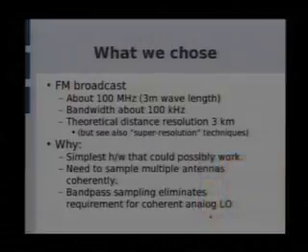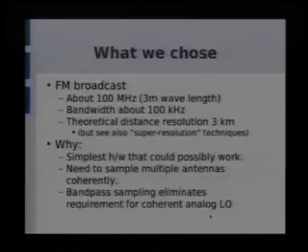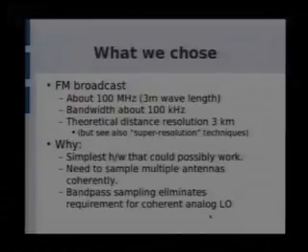So, okay, the theoretical distance resolution you get basically is the speed of light divided by the bandwidth of interest. That gives you about 3 kilometers here. Anyway, trust me, that's about the answer. There's also this other technique you can Google, follow the tips in the previous talk, on super resolution techniques. There's some great academic papers on this, and this stuff's getting applied now.